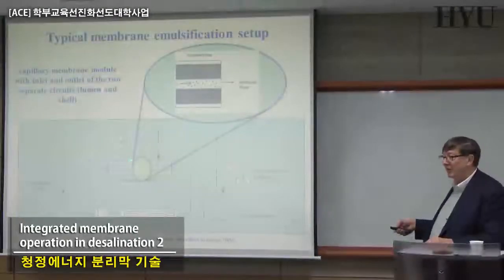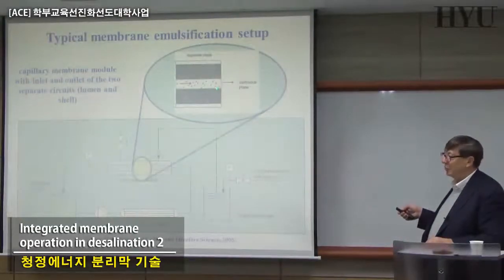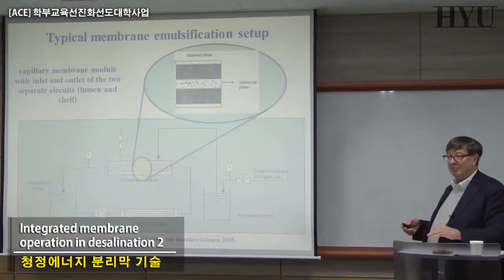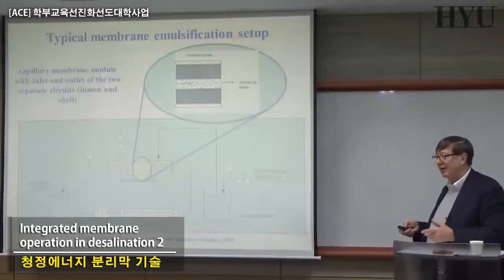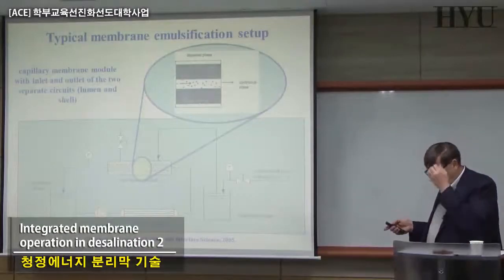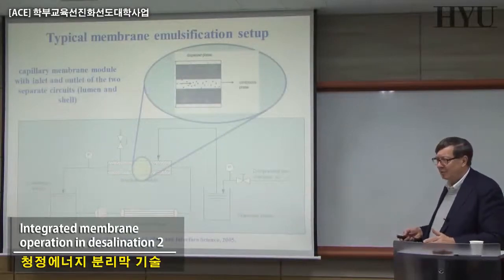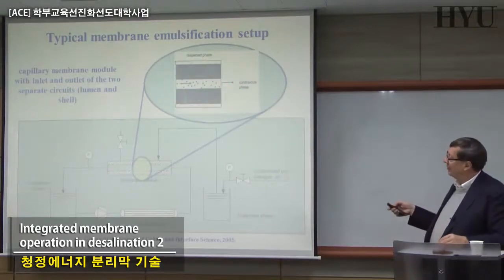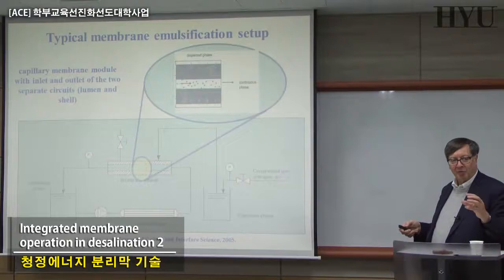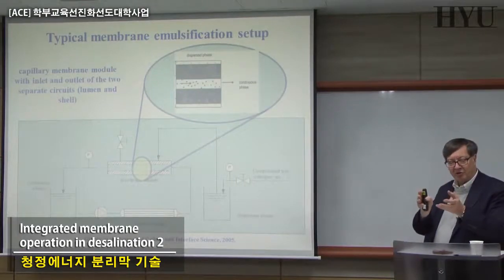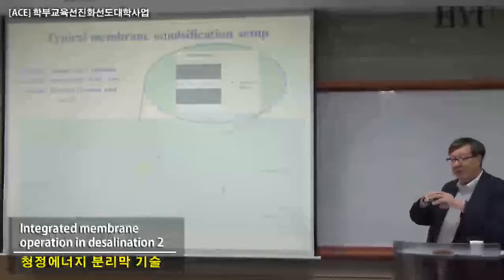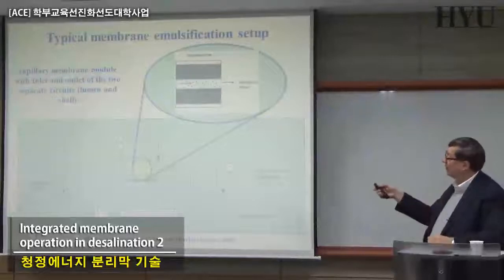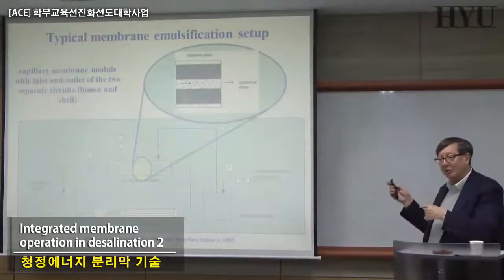If you want to predict and understand how many droplets will be formed per unit of time or per unit of surface, this is one of the most complicated problems to analyze by simulation, because you will realize the mechanism is very, very complicated. You want to predict, okay, you are pushing in, something will form here, etc. Forget it, because once the formation of these droplets starts, it will change the geometry completely depending on the cross flow. It becomes a droplet with a long tail, and the moment the tail breaks down and the droplet becomes independent, try to calculate that.